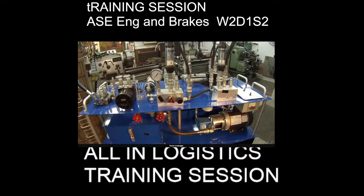So that's what makes it really simple for me to understand, and should make it simple for you guys to understand as well. Alright, the last, fluid conductors, and that is your hoses and tubing and fittings and things like that. Of course, these components wouldn't do you any good unless they're actually hooked up. You have oil tank to your pump. Then you come out of your pump with this hose right here into this block here. Then you come with this hose right here into your directional valve. And here's your two work lines right here, your A and your B work line that go out to your hydraulic cylinder. And then here's your tank line that actually goes back through the filter to the tank.